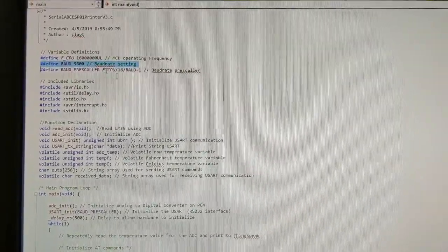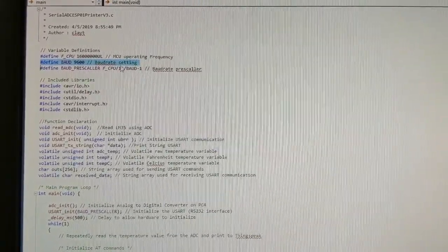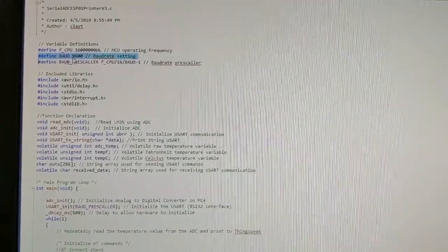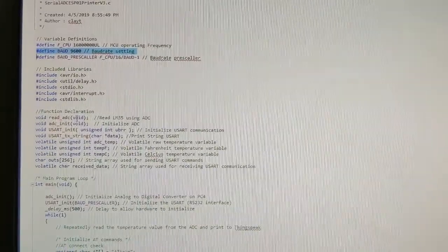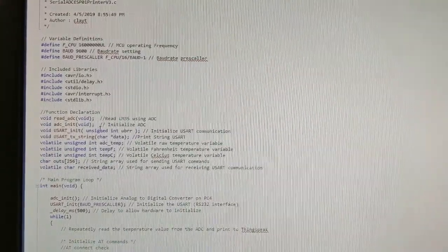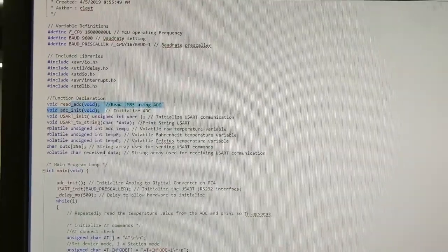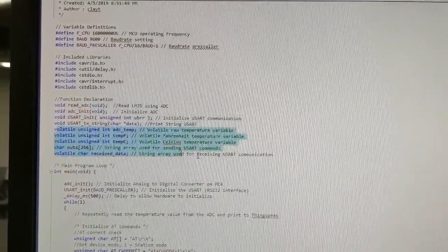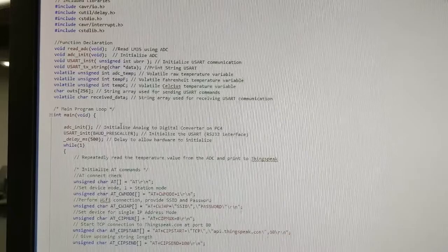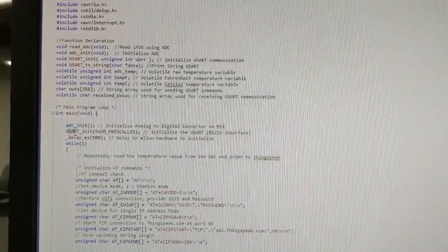We're going to do everything else on, again, the baud rate of 9600. Maybe I'll talk about that in a minute. We have to do some interesting stuff on the ESP board, and we can use that to initialize our USART communication and our ADC communication, and then I'll use that to actually take values. There's some empty location for some stuff. So, same thing here. Do initialization for both.